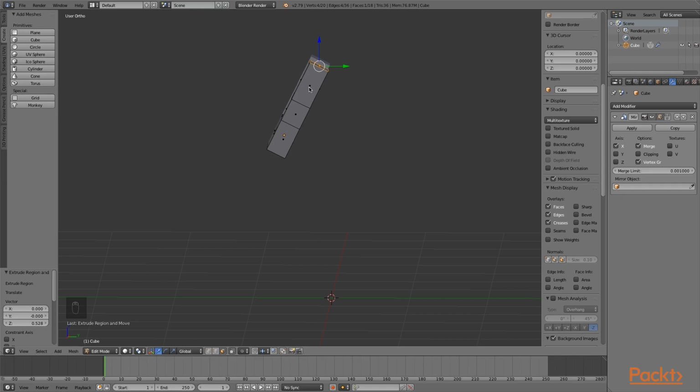You're going to hit Control R, and that's going to bring up this purple hue, which shows you that it's looping all around this square, and that's exactly where we want it. If we wanted to add more, you just roll the dial on your mouse, or with the magic mouse, I just roll up and it'll make more edge loops.